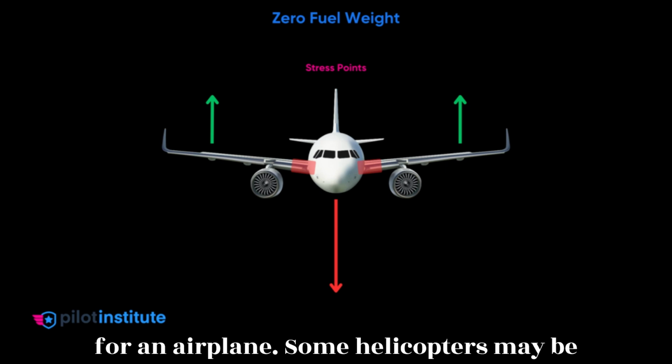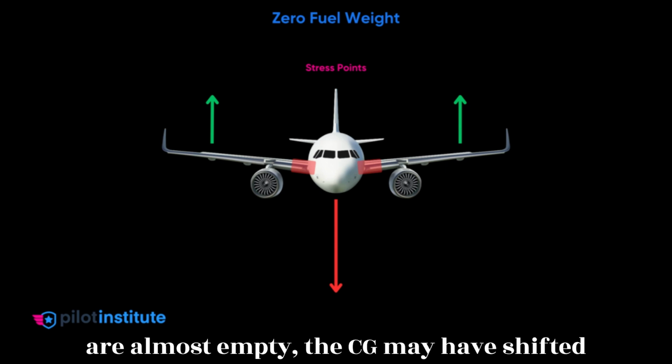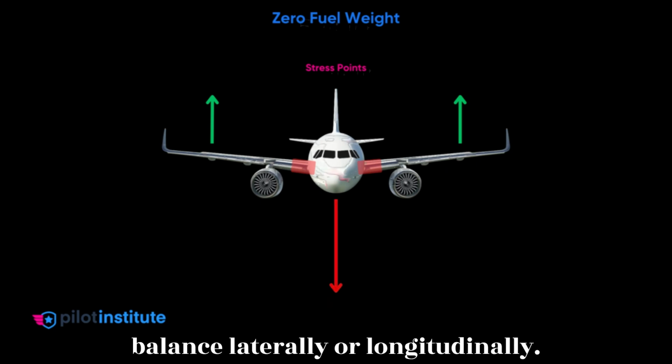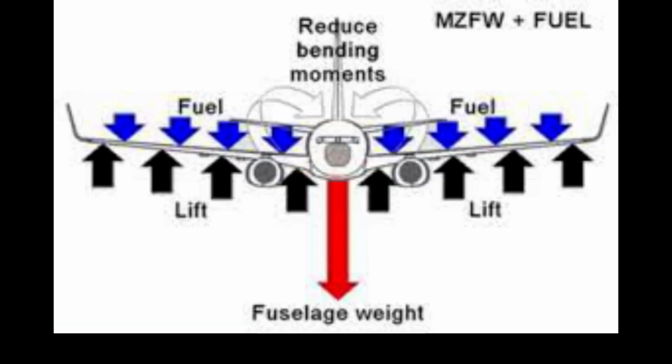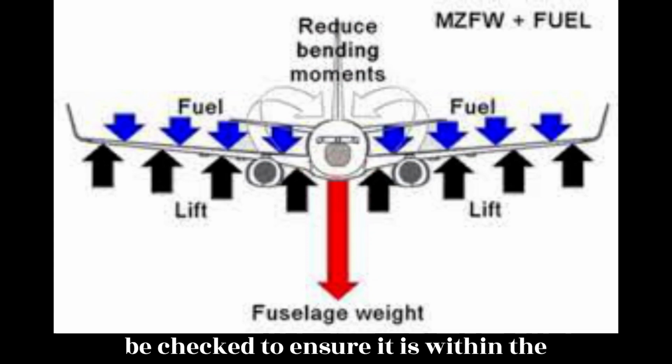Some helicopters may be properly loaded for takeoff, but near the end of a long flight when the fuel tanks are almost empty, the CG may have shifted enough for the helicopter to be out of balance laterally or longitudinally. Before making any long flight, the CG with the fuel available for landing must be checked to ensure it is